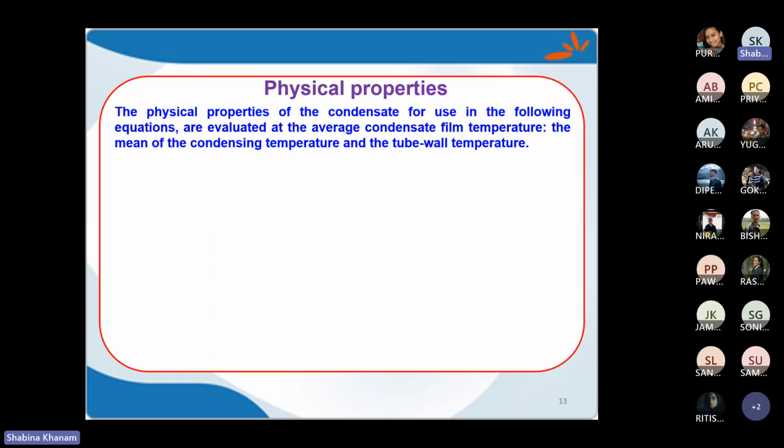However, when I consider a mixture of vapor, let's say a hydrocarbon mixture in vapor form, in which different components will be available and each component will have a different condensate temperature, because condensate temperature basically depends on the dew point. Each component has a different dew point.